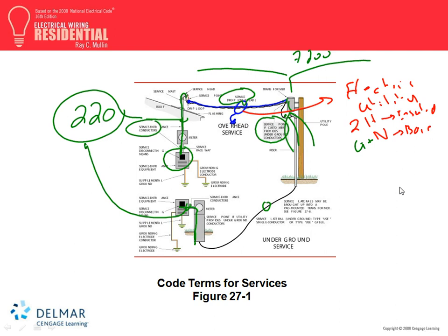equipment grounding, electrode grounding systems. You have to provide almost two grounding electrode systems in residential. I want you guys to look at this grounding electrode system and this grounding electrode system. In residential, we'll go to commercial later. In residential, most likely, almost always, you're going to end up with a rod and what? And tying the water service coming to your building.